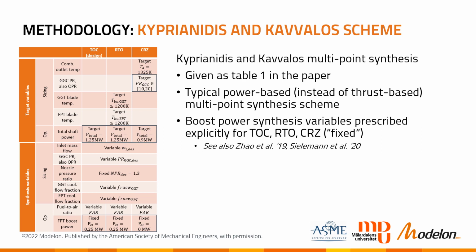And whenever we're looking at hybrids, we prescribe the free power turbine boost power explicitly, as it is done in most cases in the literature for the turbofans. You can see this at the very bottom of the table. And to the lower right, you can see a reference, the last one, if you are interested in an overview of these closure equations for the hybrids and learning about one alternative approach to define the design of parallel hybrids, please take a look at that.